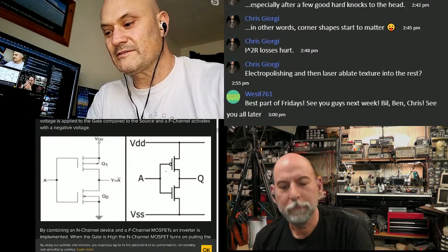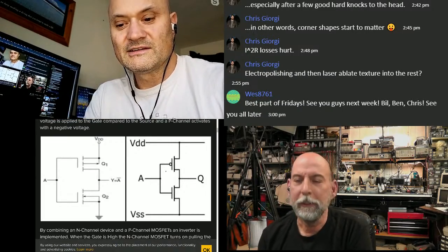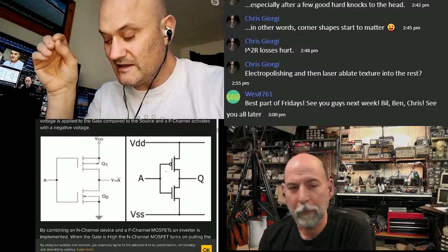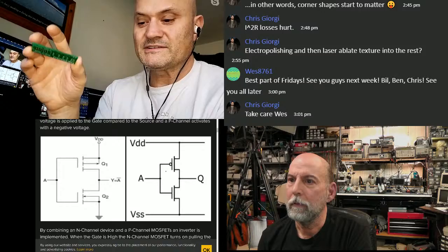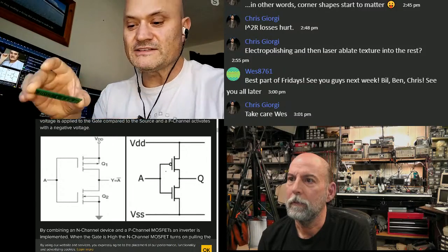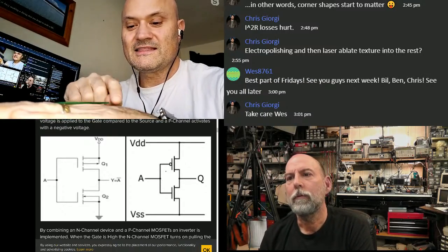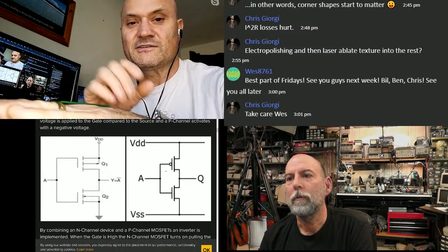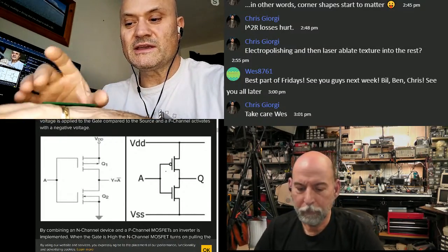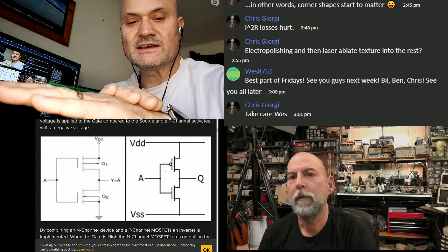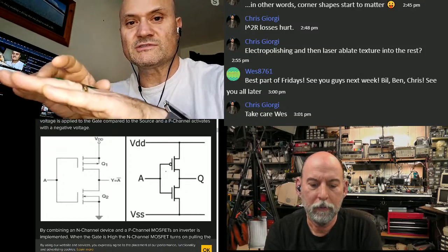You should always have some other reference, like it could just be the CAD origin in your actual layout editor. Right. You don't have to see it for it to be an origin. You don't have to see it, but you call it out in the drawings. There is one exception to that, and that's the theoretically perfectly flat surface. That's the table that the board is sitting on. There's an imaginary table that the PCB sits on facing up. Right. That is usually going to be a datum and should be a datum, because then things get compared to that, like the allowable bow and twist on the board.